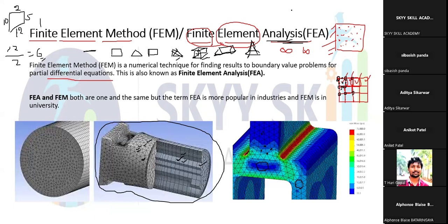If I'm going for a perfect square, then every side is going to be a. So if I'm going for a by a, what is going to get? Now 1, so it is the perfect one. But if you are getting a result in between, that is, aspect ratio less than 5, then this is acceptable, because 100% square meshes are not always possible.